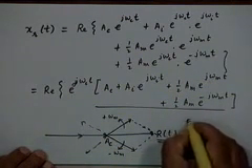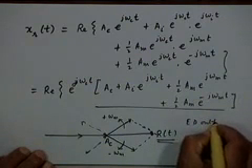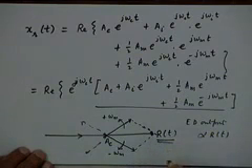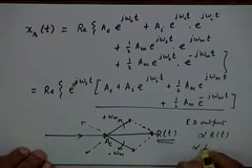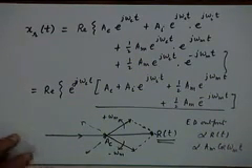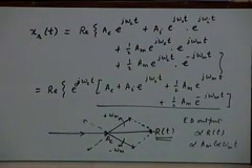So the envelope detector output here is proportional to R of t, and since R of t here will be proportional to cosine omega mt, this will be proportional to cosine omega mt, as we expect it to be, right? There is no problem about that. I hope all of you are with me on this.